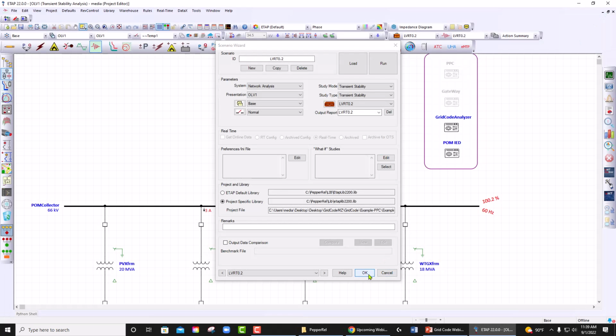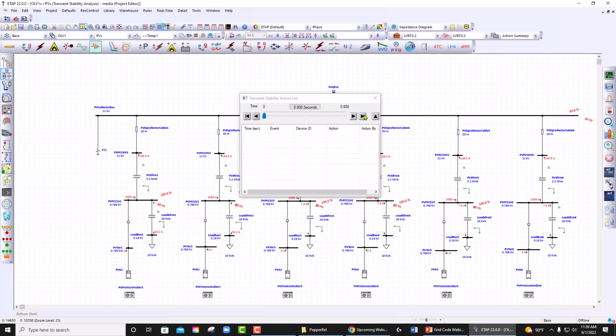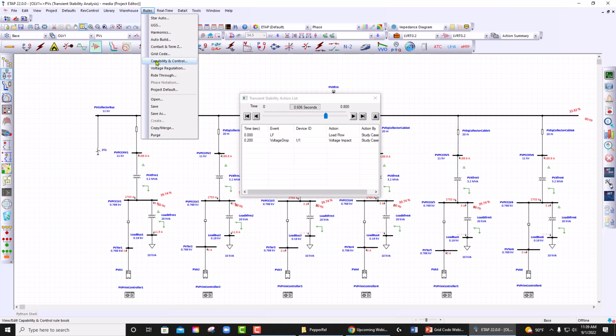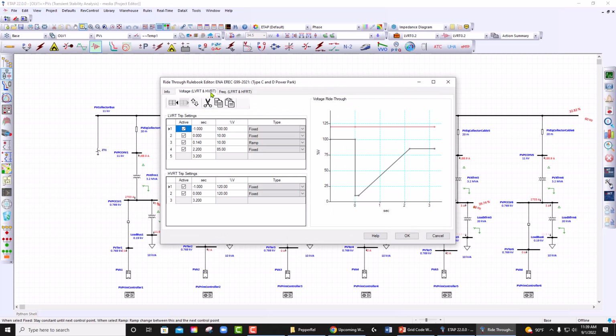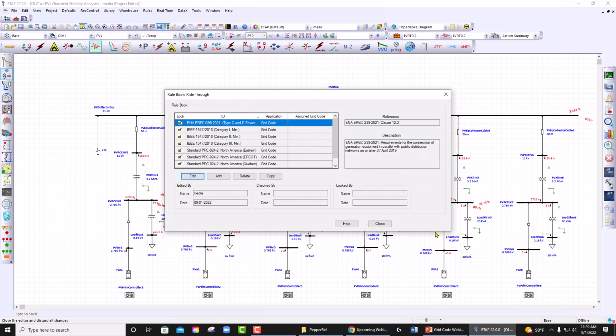So in order to verify this, you can always go to the inverter, let's say, and look at the voltage here. Voltage is around 25%, and probably goes a little bit higher. If we go, it's going to go to around 39%, because inverters have dynamic support to inject reactive power. If we go just before the fault, you see that it's around 40%. Now, if I go to my rules, go to my ride through capability, and look at the 40% voltage, it is around somewhere here, which means that it takes more than a second for these inverters to trip.